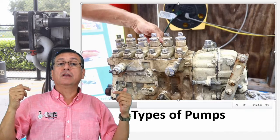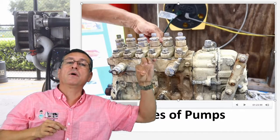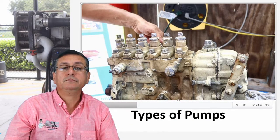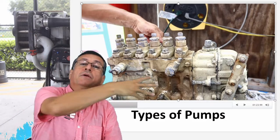The return manifold is connected with the return of the injectors. Do you remember? The return of the injectors is connected with the return of the fuel injection pump, and both of them go into the fuel tank. Because remember, only around 20% of the fuel is used to produce power and 80% returns.